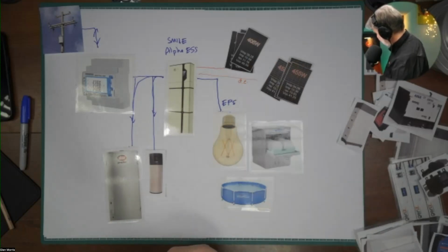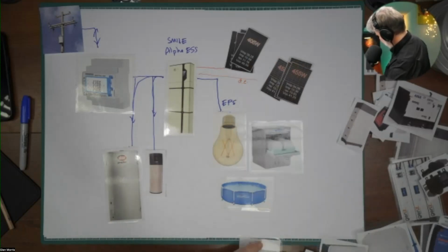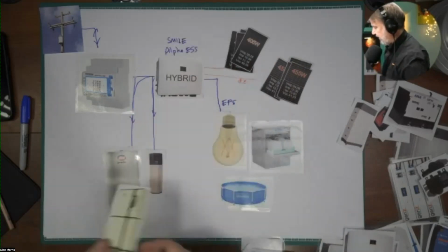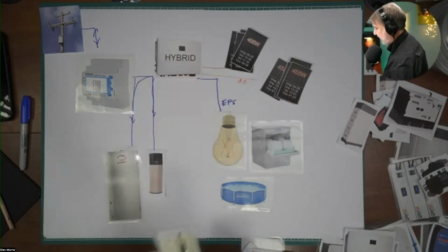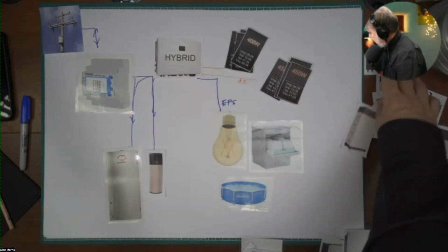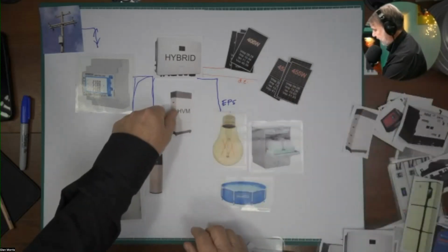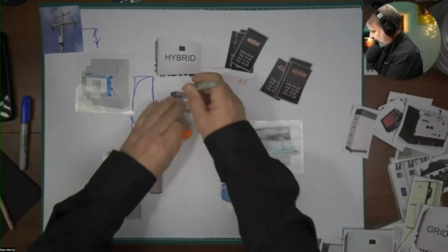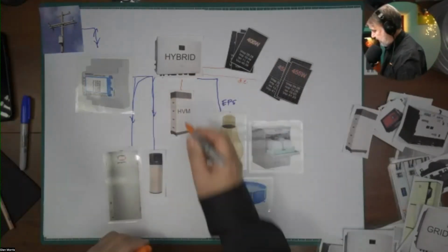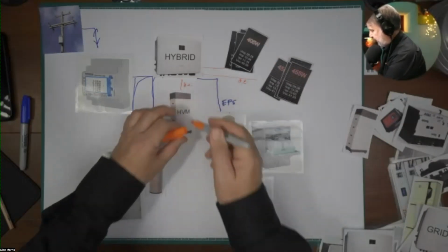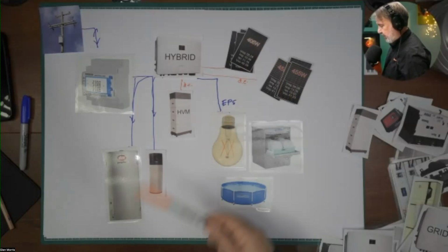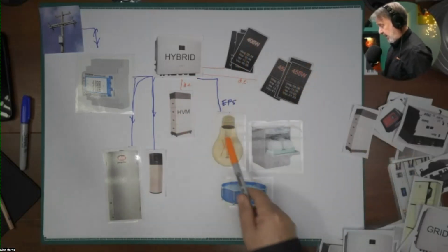So another solution would be where you've got a separate hybrid inverter like this. So that's a SunGrow. So I better cover up Smile. It's a SunGrow hybrid inverter, separate from another company's battery. So it's a high voltage BYD battery. It's one of the compatible batteries. So that's a DC port there. And it still requires a meter upstream to be able to see the amount of energy flow. It has 2 solar inputs for 2 arrays and a backup circuit as well.